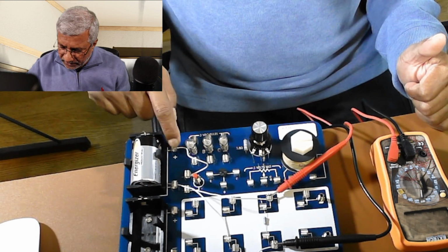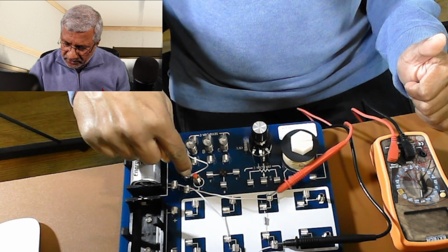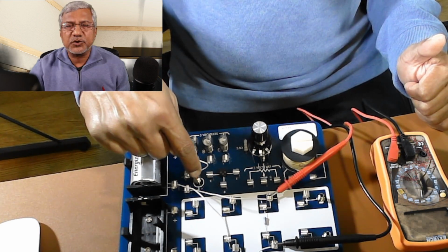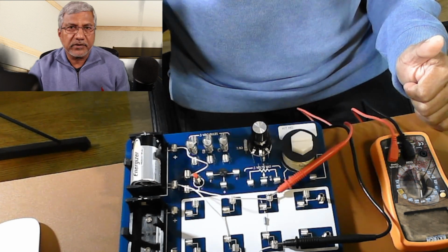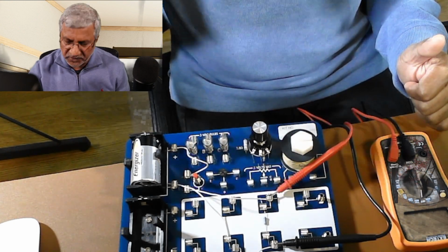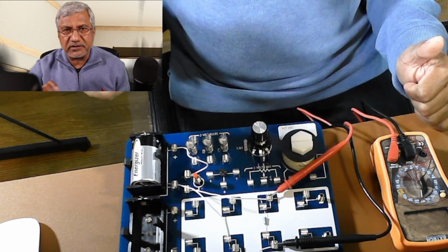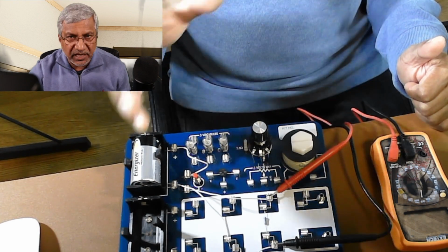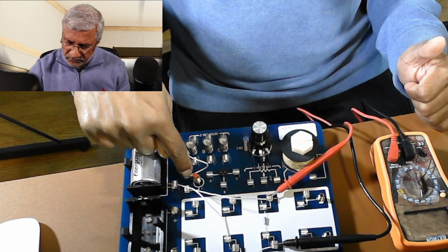And one end of this is connected to what is called SW1, because this is a switch. This switch works only if you keep it pressed down, because there's a spring inside. If you don't touch it, it's in the off position. But when you keep it pressed down, then it's on.